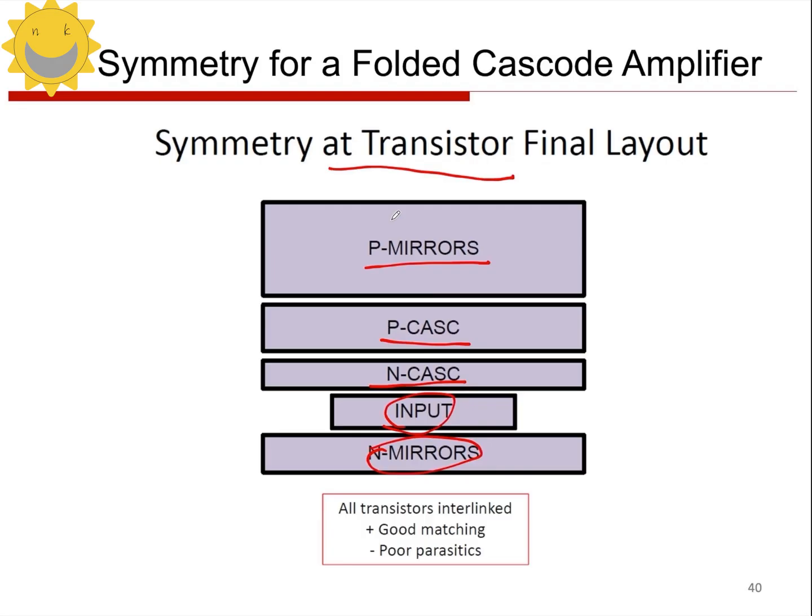So, after we arrange everything like this, what do we get? What we get is a result that has very good matching characteristics, right? We have all done the common centroid. Moreover, the corresponding parasitic lines definitely need to be arranged properly, right? So, in this way, we achieve very good matching characteristics.